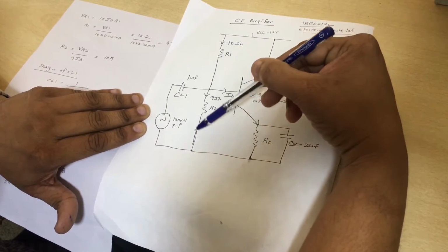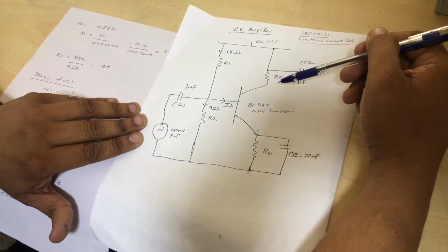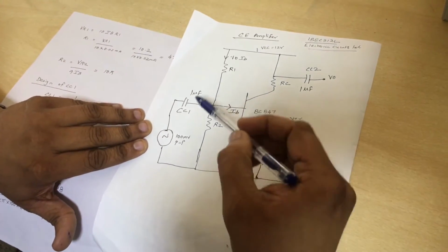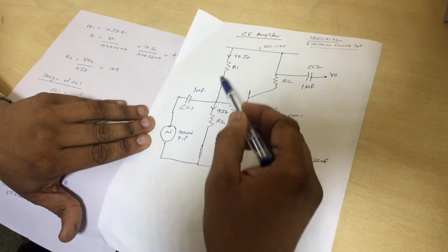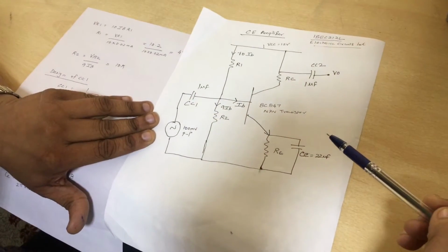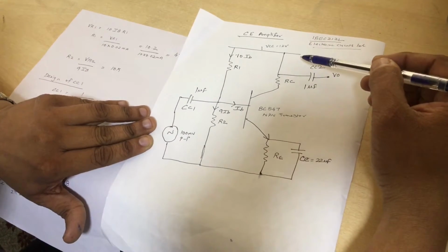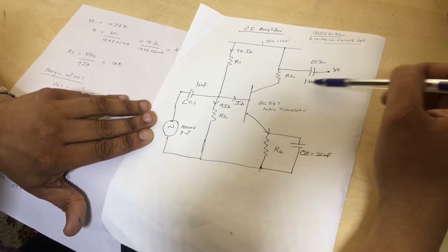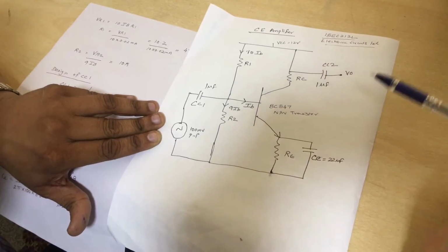Basically, we know that we go for biasing to ensure that the transistor remains in the active region and the Q point is fixed. And we are using certain capacitors here. The role of the coupling capacitor is to isolate the DC condition, that is, the DC voltage should not flow to the input. Similarly, we have the output coupling capacitor, basically to isolate the next stage. We want to isolate the DC condition of the first stage from flowing into the second stage.